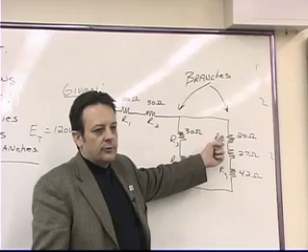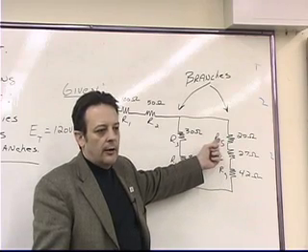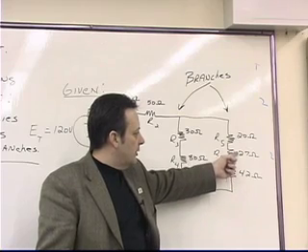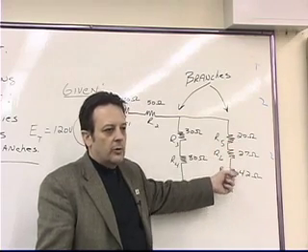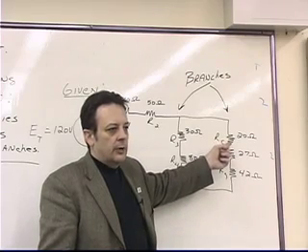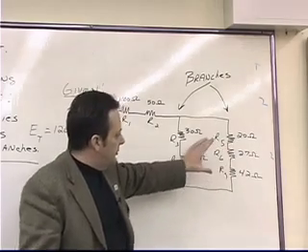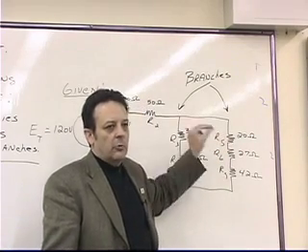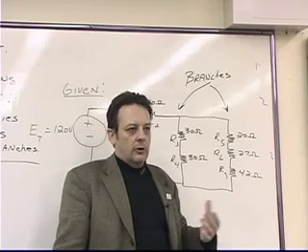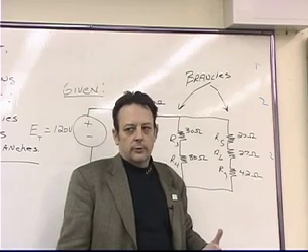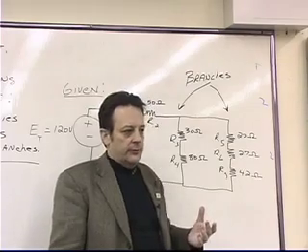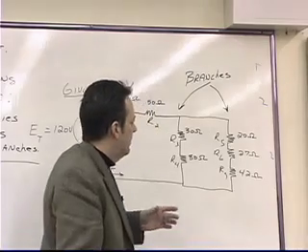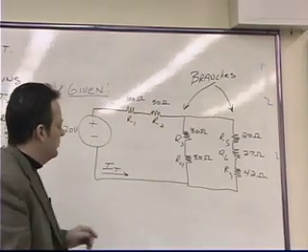We find three resistors, R7, R6, and R5. We can see that those resistors have a value of 42, 27, and 20 ohms, and they're clearly all in series. Okay? So would it be fair to say that we could substitute those three resistors with one single resistor and wouldn't affect the electrical characteristics of the circuit at all? Right. It would affect the topology of the circuit. It would look different, but it would not react any differently electrically. Okay? So that's our first step. Our first step is to do that.